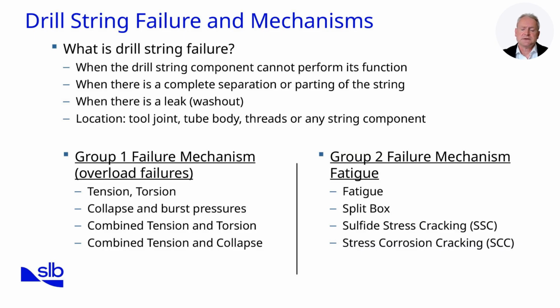Common contributors to fatigue include doglegs in directional wells, high rotary speeds, and vibration. Fatigue accounts for more than half of all drill string failures, making it the most significant mechanism to address. Other mechanisms include connection wear, corrosion-assisted cracking, and handling damage on the rig floor.